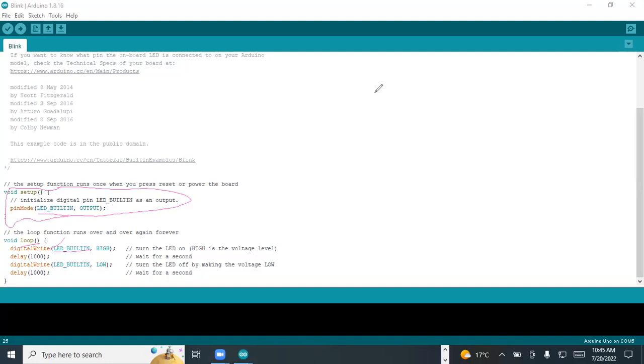And then we are putting a delay of 1 second there. Thereafter, we use a digitalWrite with a LOW signal to that pin. That one will basically switch off the LED. And then again, we put a delay of 1 second and we end the program there. So you can see now there's this section, which is the void loop part, and then there is that section, which is the void setup part.